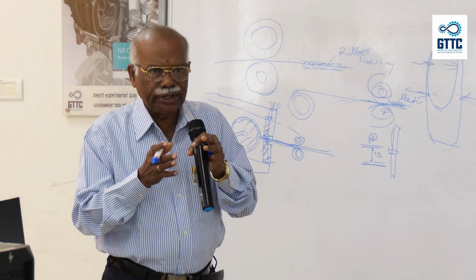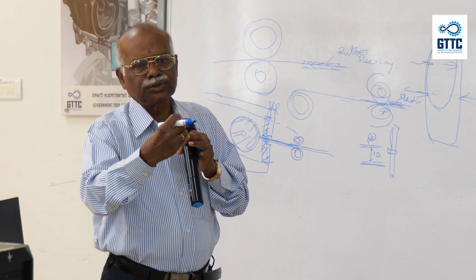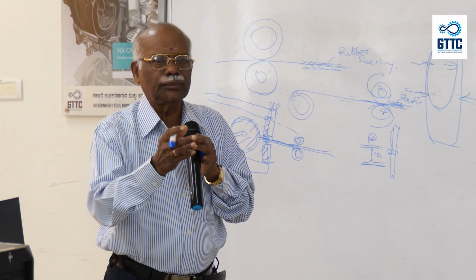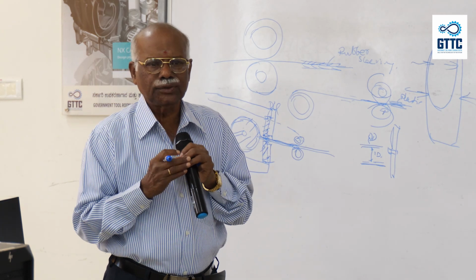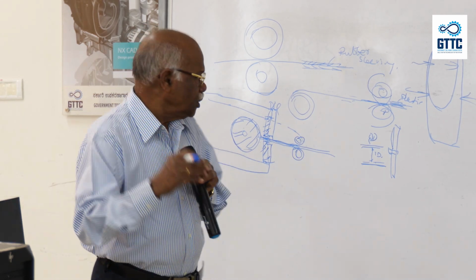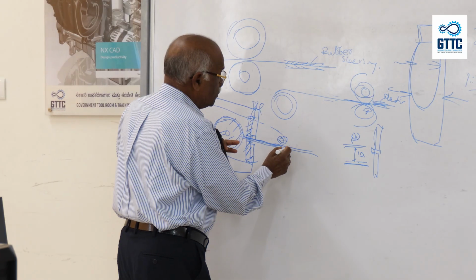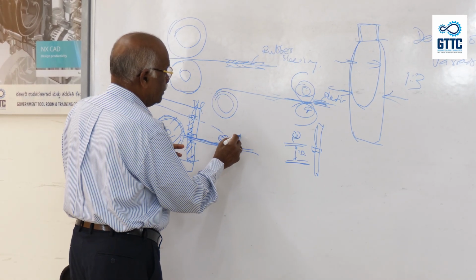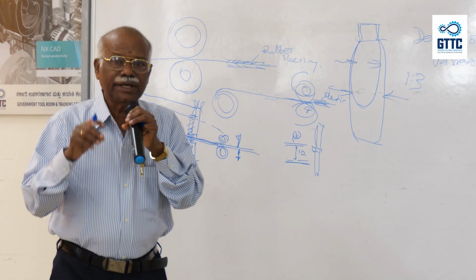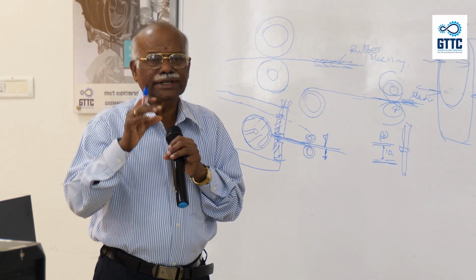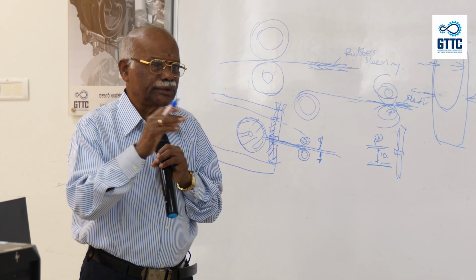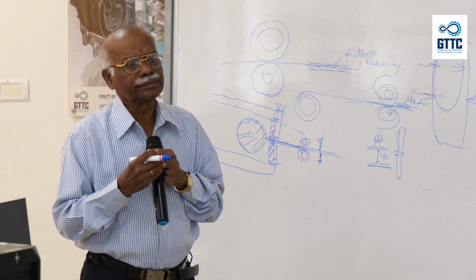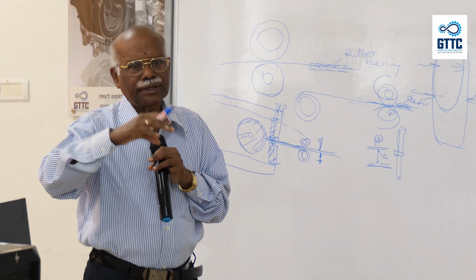The material will flow through, and at the end there will be a small nozzle-like part called the mandrel, through which the material flows on the outside. By vacuum, in this area, a vacuum pressure is created to maintain the size of the pipe. No deformation takes place. Immediately it is cooled in cold water, so that the diameter is held.